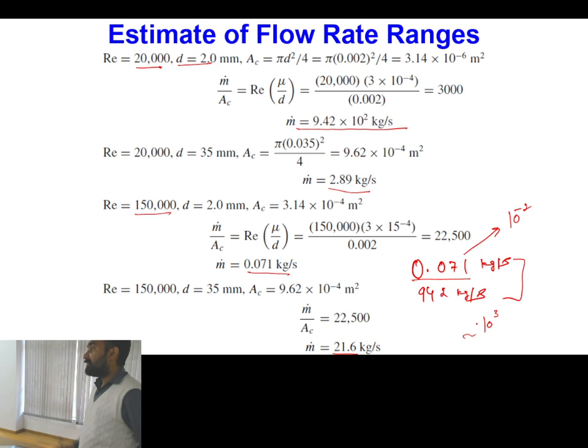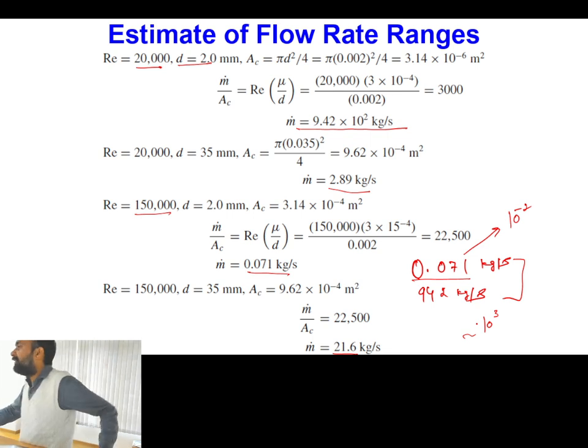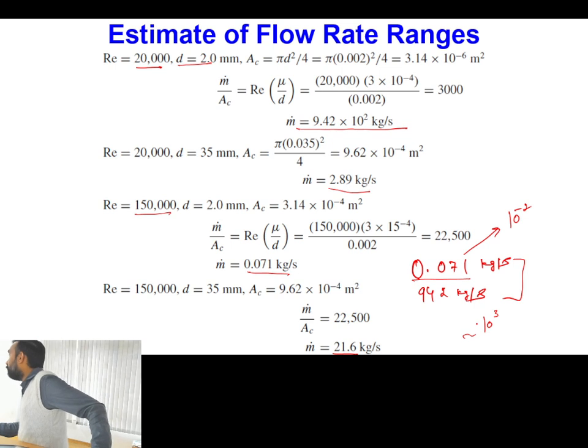Okay. So it means that you need a flow meter which can measure the mass flow rate in this wide range. Okay. So obtaining this type of flow meter will be actually extremely challenging, because typically, if you take a device with that much wide range, then sensitivity of that particular device will be low, and particularly in the low mass flow rate region, whatever reading it will be giving will not be accurate enough.